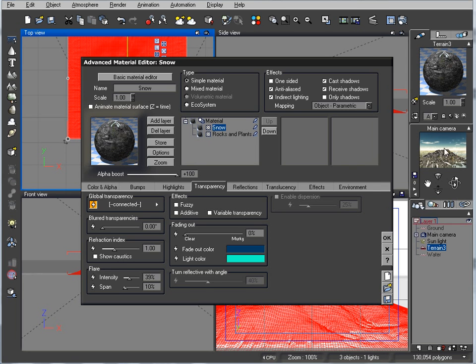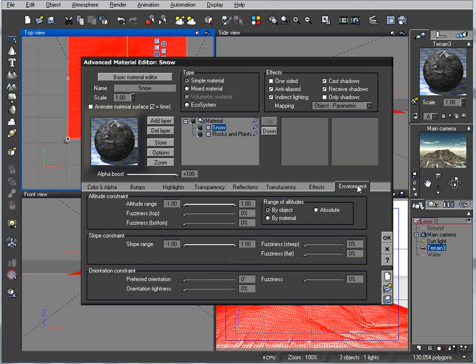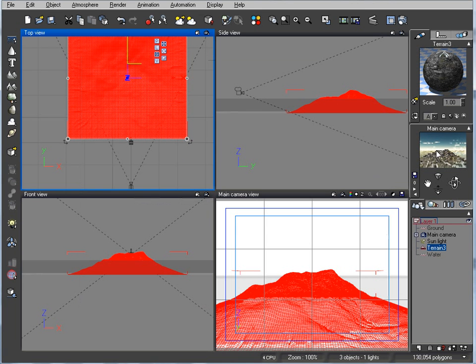Okay, our transparency, again, if you remember, now the material will be more translucent depending on the grayscale of our image. Whatever image is applied right here, if we have a grayish area, it will have more transparency, and in dark black we have maximum transparency. And again, in this case we can apply all other effects as we apply to the layer. Again, this is another way to add your material mapping based on an image.